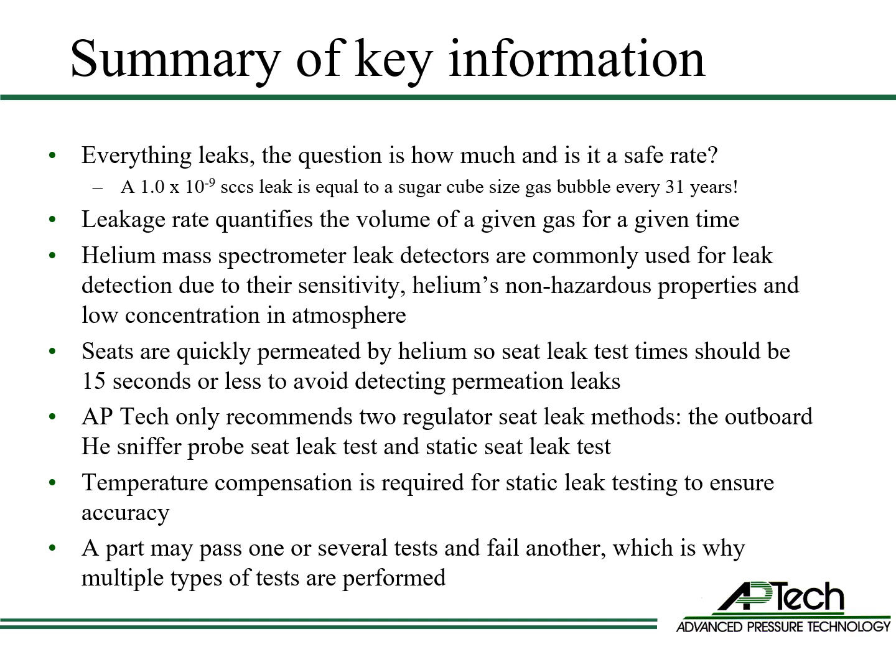Helium mass spectrometer leak detectors are commonly used for leak detection due to their sensitivity, helium's non-hazardous properties, and low concentration in atmosphere. Seats are quickly permeated by helium, so seat leak test time should be 15 seconds or less to avoid detecting permeation leaks.